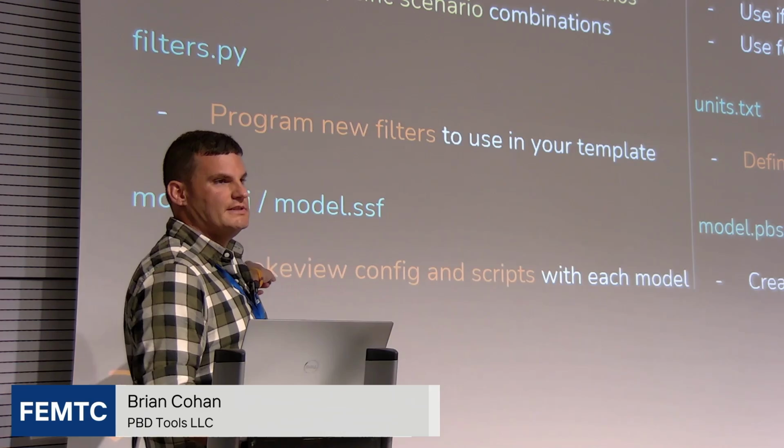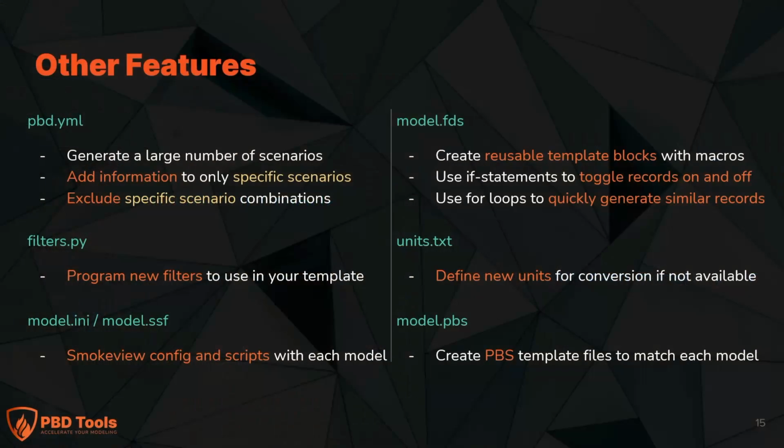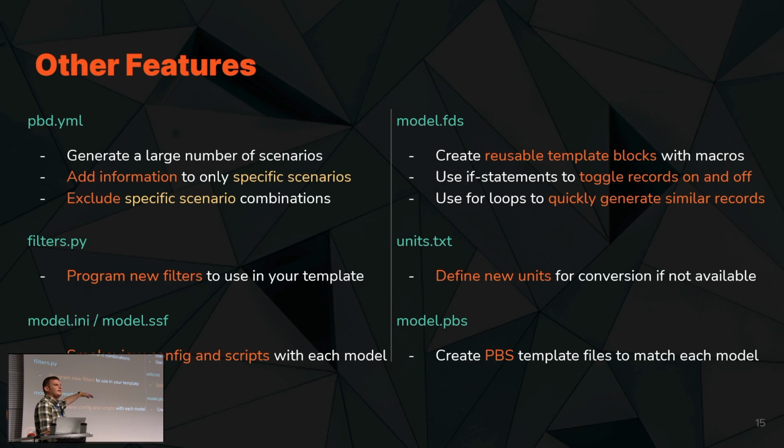If you notice the slides all had a consistent aspect ratio, you can set your smokeview.ini file with certain parameters, so that as soon as you open SmokeView, it loads that and says, okay, you want this to be this tall, this wide, have this view, turn on this slice, all that stuff.